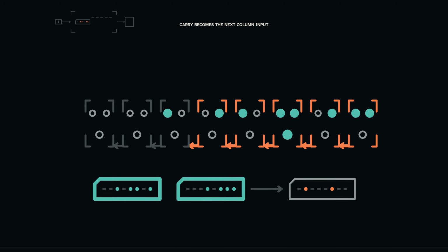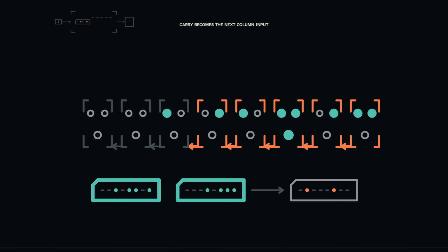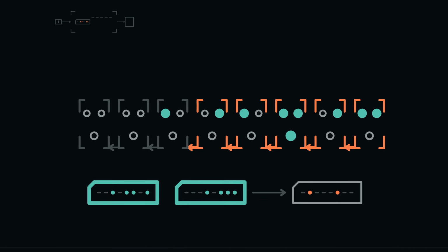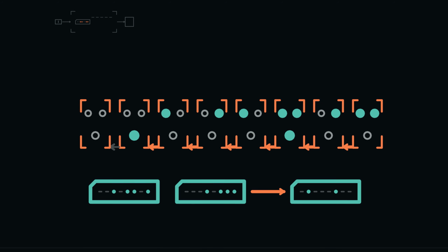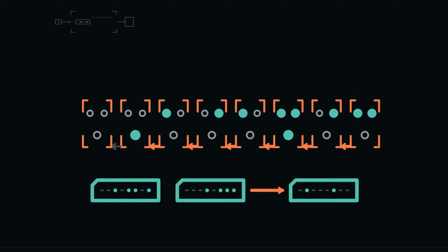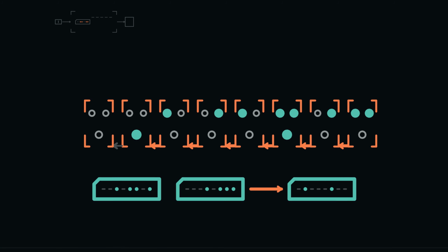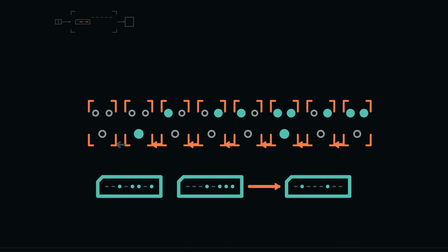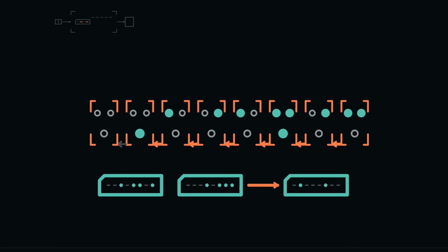The lower half of the result is 0100 when read from bit 3 down to bit 0, but the operation is not finished because carry still enters bit 4. Continue from the preserved carry. At bit 4, 0 plus 1 plus carry gives sum 0 and carry 1. At bit 5, 1 plus 0 plus carry again gives 0 and carry 1. At bit 6, 0 plus 0 plus carry gives sum 1 and carry 0.